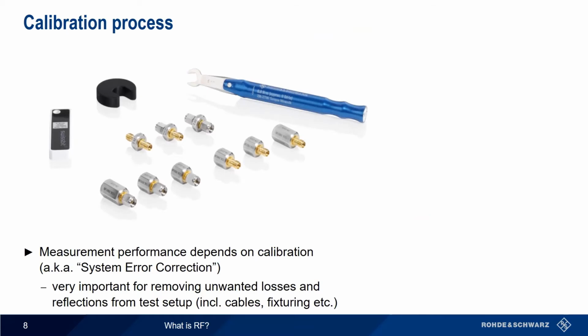Typically, VNA calibration involves connecting test standards representing a short circuit, an open circuit, and a 50 ohm load or match to each test cable as prompted by the calibration routine, and then inserting a through standard to the end of the 2 test cables.